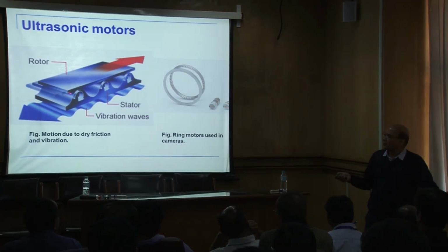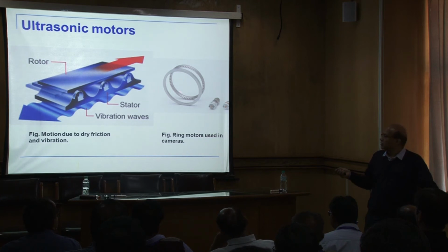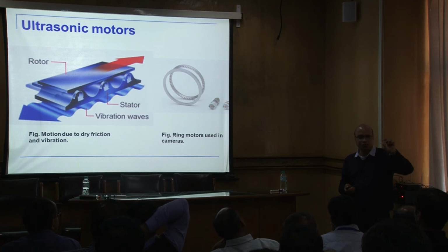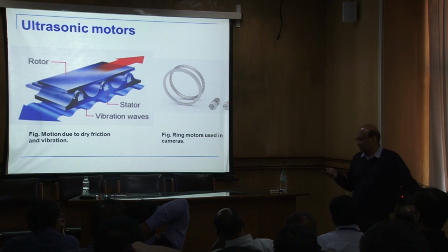Yes. Now this is in physical contact with that, and there is friction there. So the torque of this motor is very high compared to a DC motor. So the torque of these motors is much more than DC motors. But they work in steps. So if you carefully notice when a camera lens goes out or it comes in, it moves in small steps, very discontinuous motion. So that is an indication also that the motor inside is not a DC servo. It is something like this.